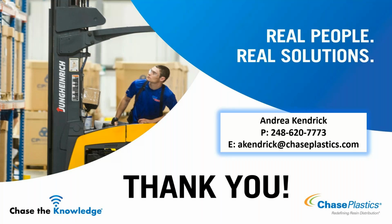Yes, I will. Actually, on the next one, I believe we talk about reinforcements as well, and I did a whole presentation on reinforcements. But a very nice quick answer would be glass adds to the stiffness and strength performance of the material. On the flip side, it typically tends to decrease your elongation and your impact performance. So if you're making some type of structural component and you need better stiffness and strength performance out of it, you can add a little glass.